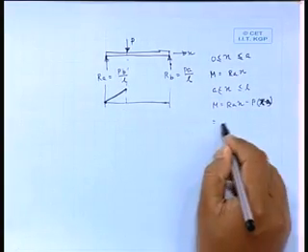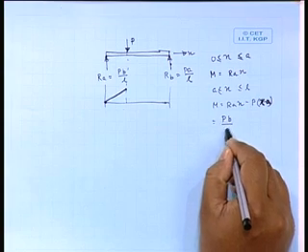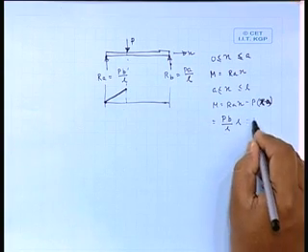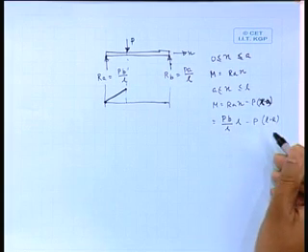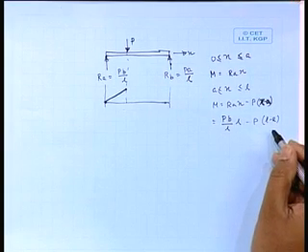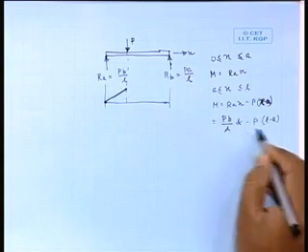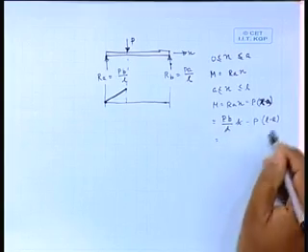So, rather I can put R A equal to P B divided by L, say at x equal to L, minus P into L minus a. L minus a is equal to b, and this L cancels. So it will be P b, and automatically it will cancel and be 0, a special case.